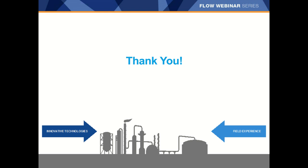It may surprise you to know that the different regions of the world have different specifications. I mentioned this earlier, but the LNG heating values required in these different markets don't always overlap. Lean LNG with a high heating value that's lower than 1,065 BTUs per standard cubic feet is used in North America and the UK, whereas rich LNG is often used in the Far East markets that might range from 1,090 all the way up to 1,170 BTUs per standard cubic feet. So some LNG in European markets may even be as low as 990 BTUs per standard cubic feet.